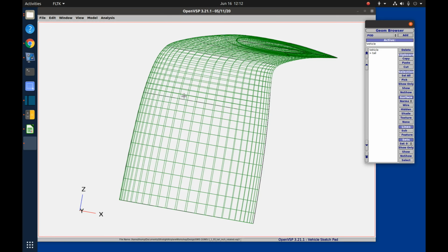In reality, it's yawing to the right, but in order to get this calculation done, we're calling it pitching up. So the free stream air is coming in from the left horizontally, and then the rudder is deflecting down. So that increases the camber even more, increases the lift of the vertical stabilizer even more.